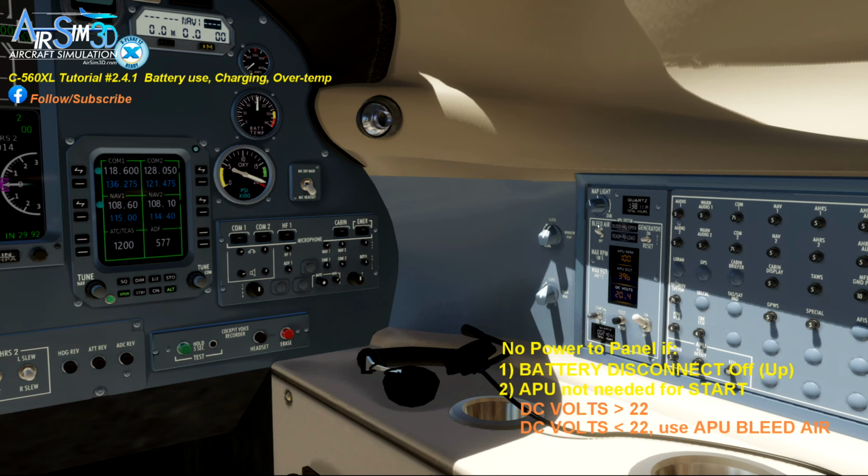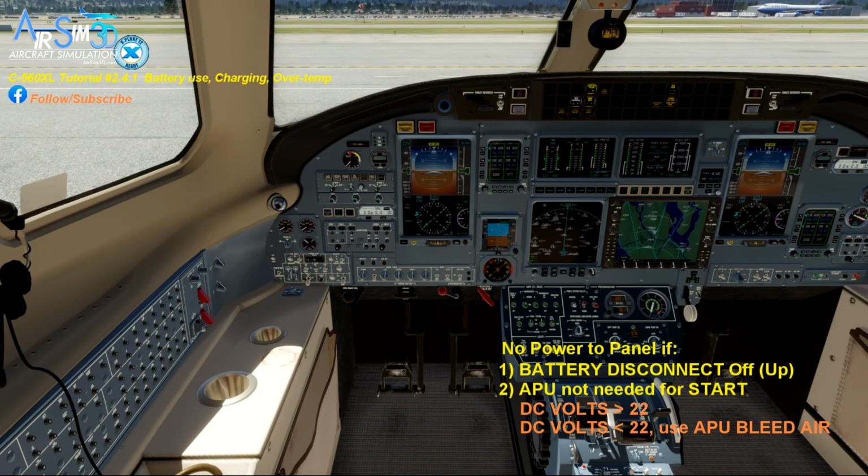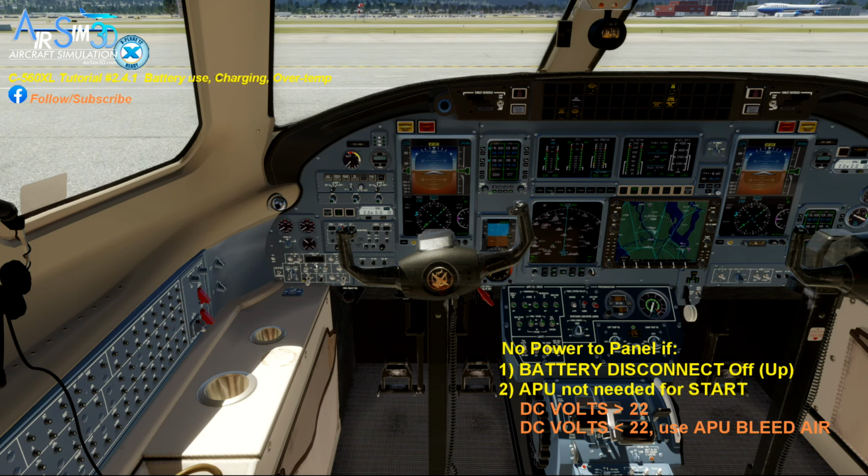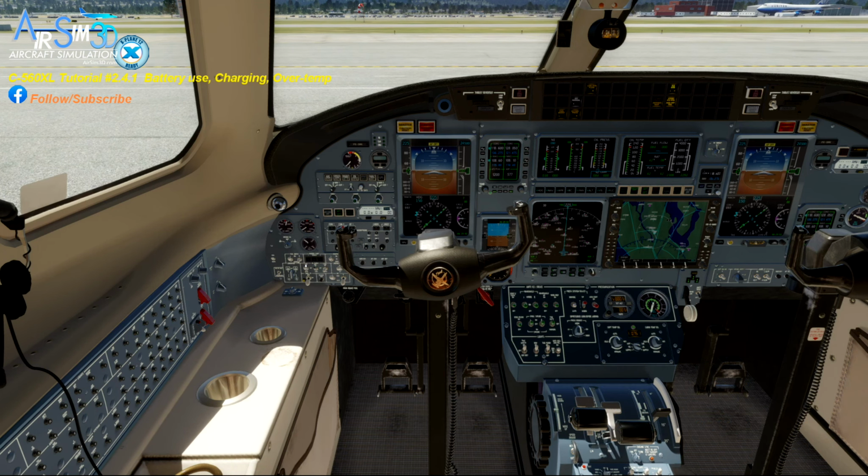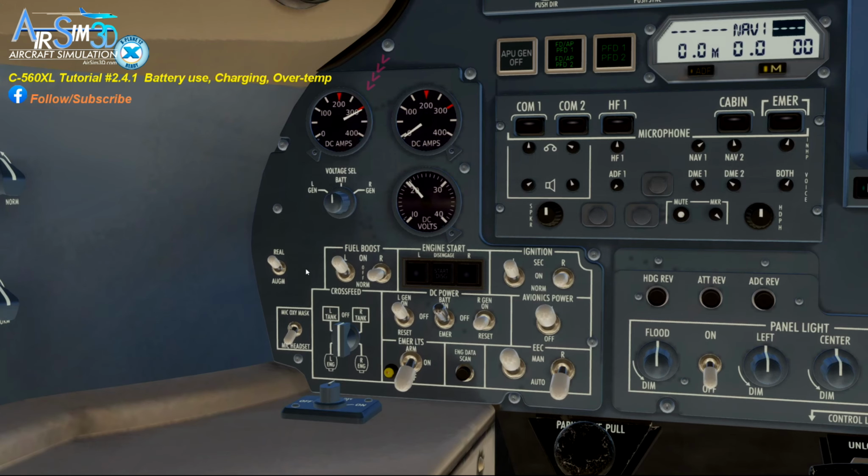And going one step further back to the more overarching electrical side of things, once an engine is running and stable, only then should you turn the engine's generator switch on and watch the amp meter. If the battery is low, the charging rate from that single operating generator will be quite high.